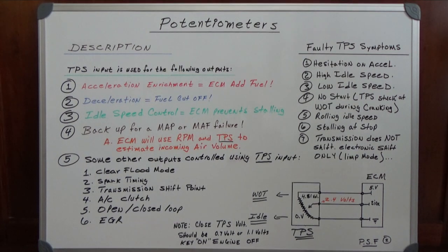This is a chart that I make here for potentiometers, also known as the TPS, accelerator pedal. This is the description. TPS input is used for the following outputs: acceleration enrichment, ECM adds fuel. Number 2, deceleration fuel cutoff.